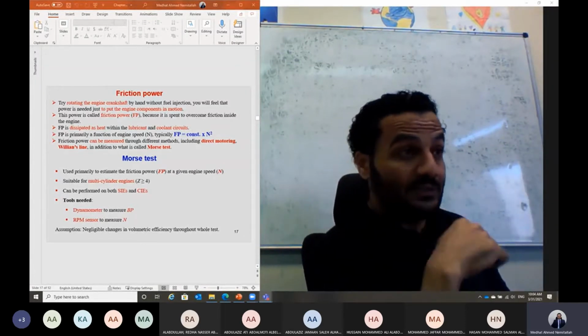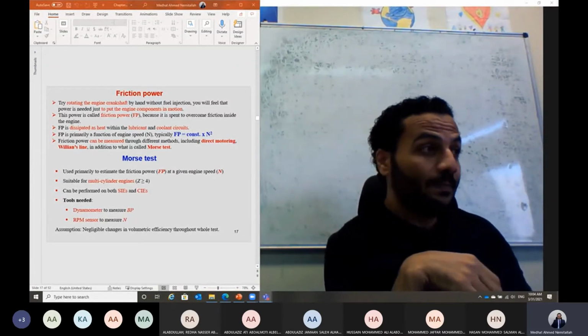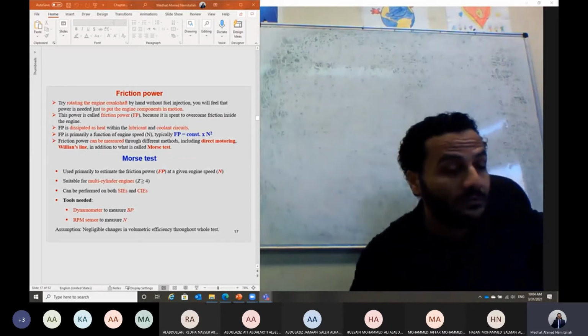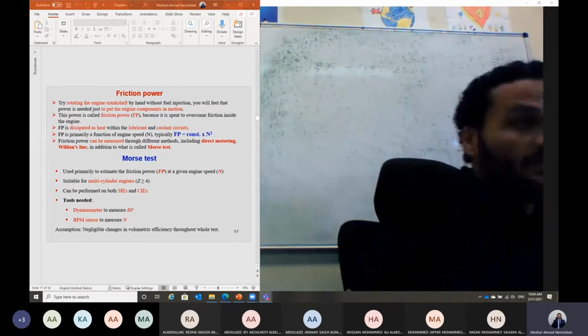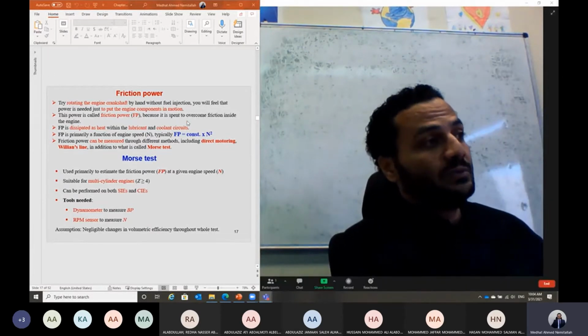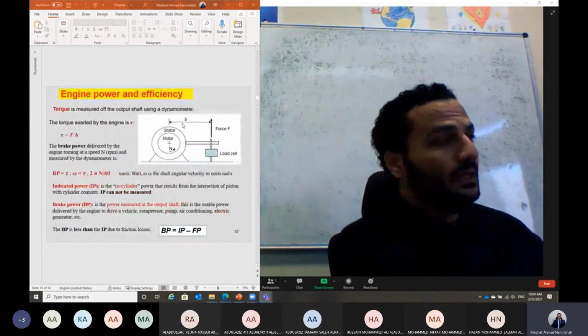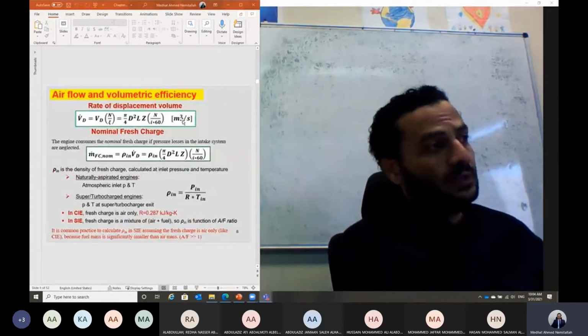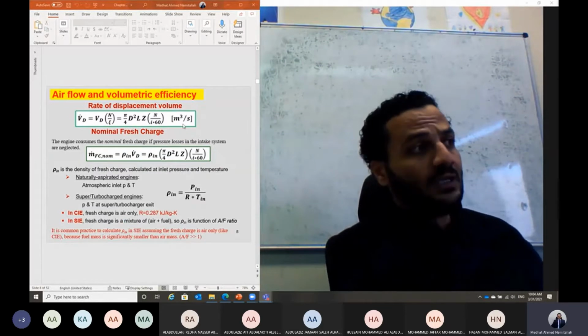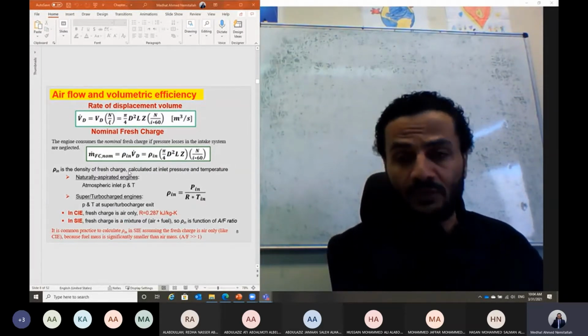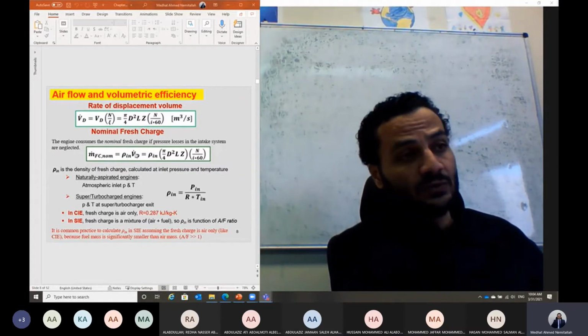It will be discussion. Inshallah today we'll continue our talk. Last time we started our talk about the engine performance. Last time we talked about how we calculate the displacement volume in terms of the engine CC multiplied by the number of cycles per second, and how to calculate the mass flow rate of air per cycle in terms of the displacement volume multiplied by the density of air.